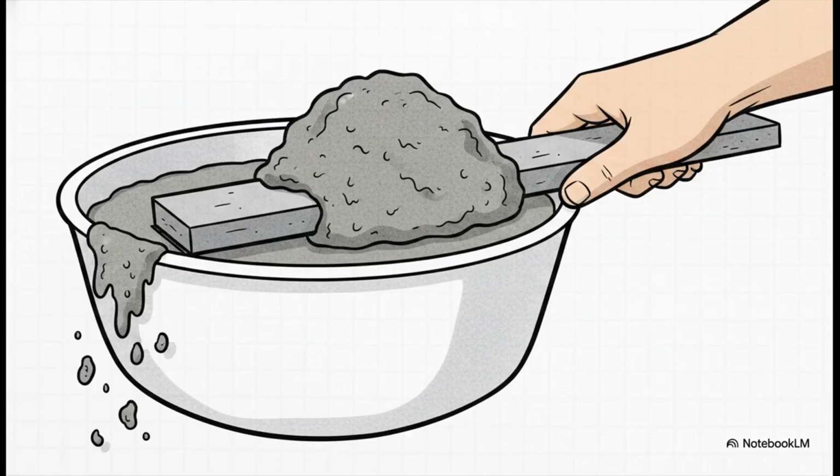Once consolidated, we must perform the strike-off. You take that steel strike-off bar and finish the top surface so it's perfectly smooth. The standard is incredibly specific here too. An excess of concrete protruding approximately 3 millimeters above the top is considered optimum before striking it off. The entire goal is to leave the measure perfectly level and meticulously cleaned off on the exterior. It has to be perfectly flush, ready for the lid, so the volume is absolute. It's actually a really satisfying step.